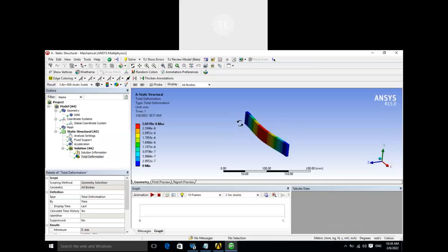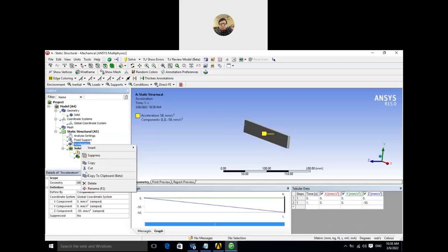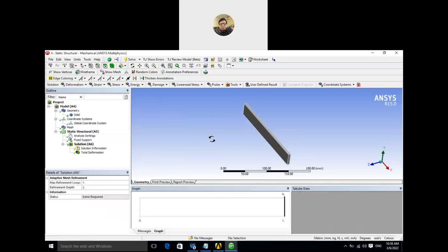So this is this. Now I delete the acceleration load. On the same model, I give gravity load. Whenever, like 1G, 2G, standard Earth gravity. Value applied coincides with the selected unit system. That means whatever the unit system, it will coincide with the unit system. It is defined along one of the three global or local coordinate systems.